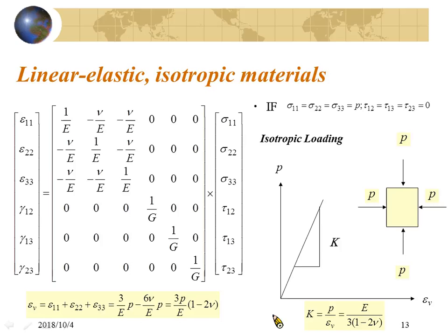If you expand this and delete the higher order terms, you will have this relation. Sorry, it should be 1 minus this. So the volumetric strain will equal epsilon 11 plus epsilon 22 plus epsilon 33.